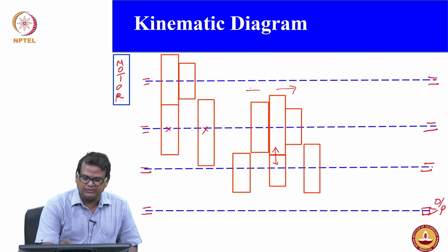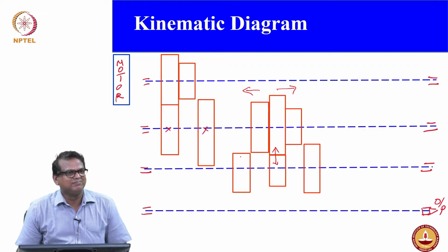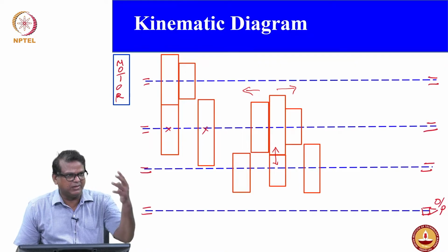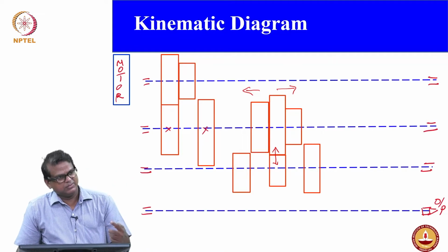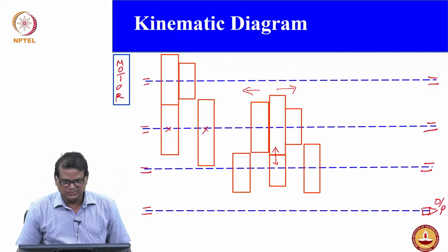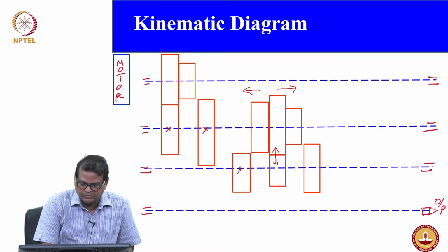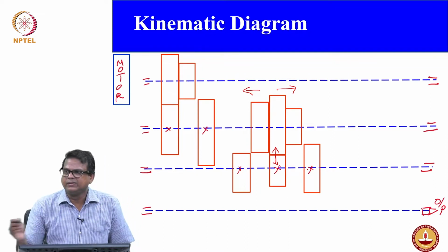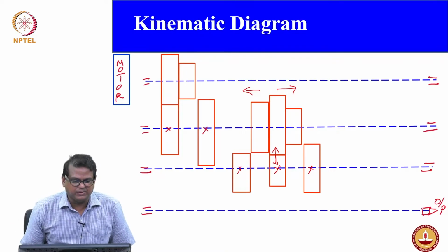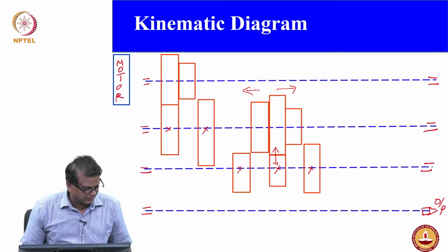Again if I shift the gear to engage these two, I would expect the medium speed in between, right? So we have already given the 3 ranges for F, and so does G, right? Be aware that these gears are fixed, only the drive gears are shiftable, movable, okay. So this is your arrangement for the stage 2 kinematic diagram, okay.